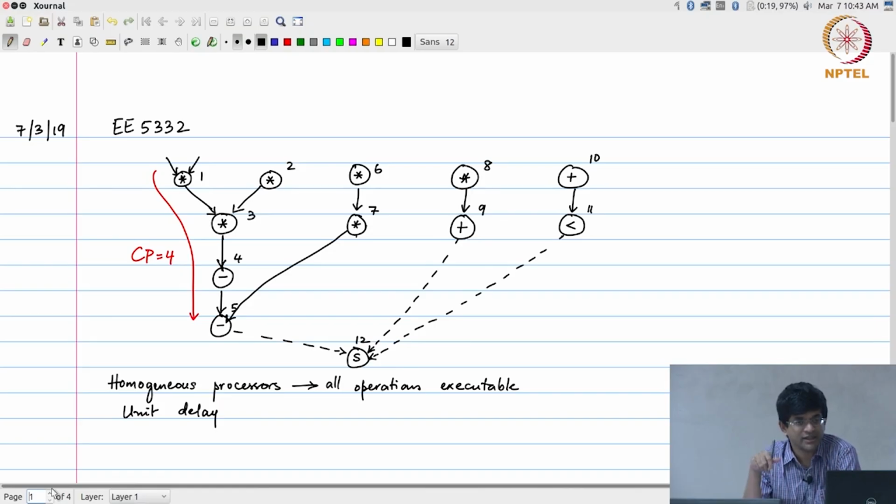The second thing that actually determines this is, even if you have the necessary hardware, will you be able to do it subject to the time constraint that you have, right. In other words, let us say that I want this entire thing to operate at a clock period of 20 nanoseconds, I might find that chaining two operations together into a single clock cycle is easy to do. But if I had to do it with a clock period of 2 nanoseconds, I might find that it is very hard to do, and I have to pipeline the multiplier and adder separately, and I can't chain two of them into a single clock cycle.